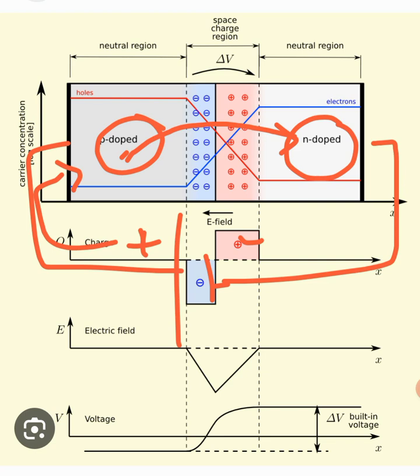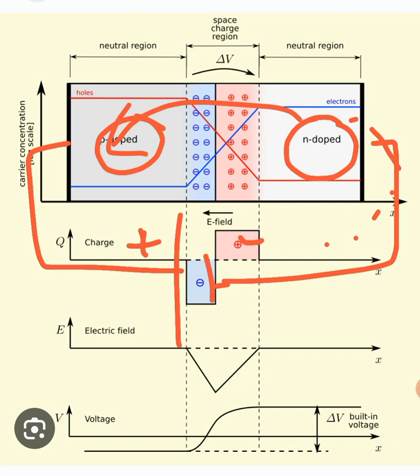In other words, we say the electrons will be pushed from the N type material, and they will travel to the P type material after the electric field that we apply externally overcomes the internal barrier voltage of the PN junction.